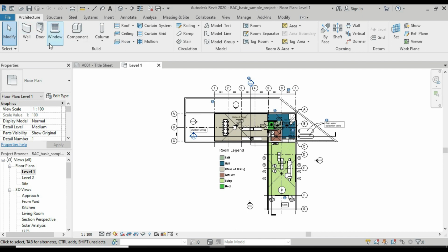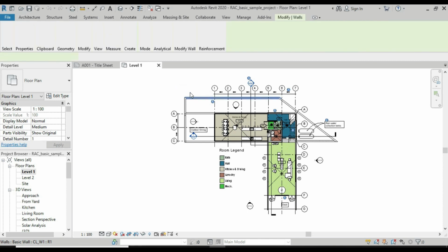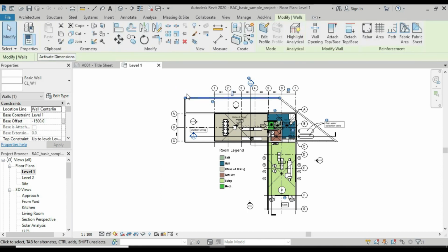Okay. Then, once we click this wall, the properties of our ribbon will change. We call this line the option tabs. With the option tabs, this is where you edit some parts of the elements. We call the things we put in our drawing elements.